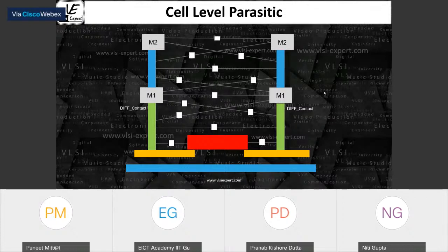Then we have to do all this parasitic extraction at the device level, and I have to understand where the problem is, whether the devices are interacting with each other, and whether the problem is because of the device level extraction. Since I was in that particular team only, we always suggested, you have to make a different layout, you have to place this differently, this is because of this particular device. So in a lower technology node, it affects a lot.